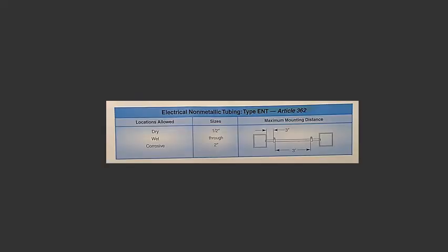Electrical non-metallic tubing. A newer type of plastic corrugated raceway called electrical non-metallic tubing, or ENT, is now recognized for general use by the NEC under Article 362. It is flame retardant and is resistant to moisture and chemical atmospheres. ENT can be used in almost any building or dwelling regardless of height and can be concealed behind walls, above ceilings, or embedded in concrete.